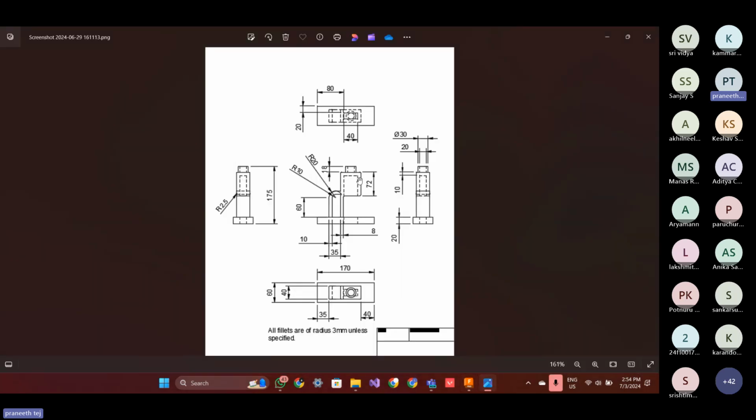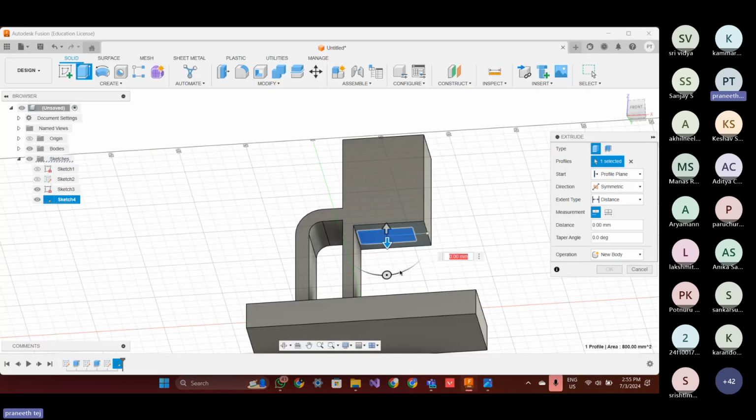Till here you can see the hollow part with the dashed lines. From the bottom the total is 72. From this sketch you can see the upper part is 10. So the whole length from the dashed lines to the base is 72 minus 10, which is 62. So the length we have to extrude up is 62, and downward we extrude till where it gets hollow.